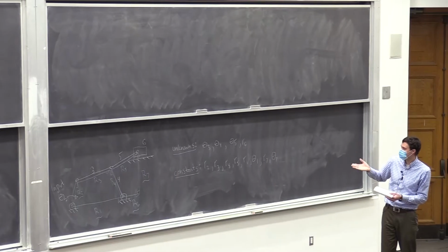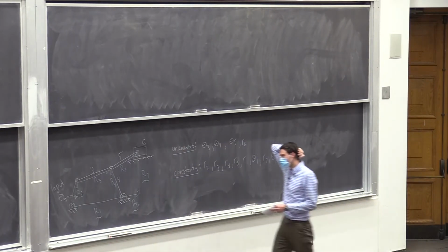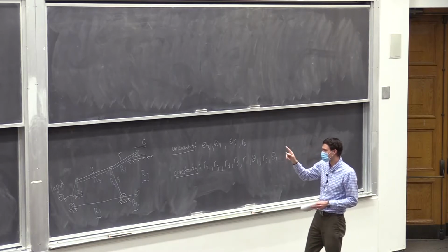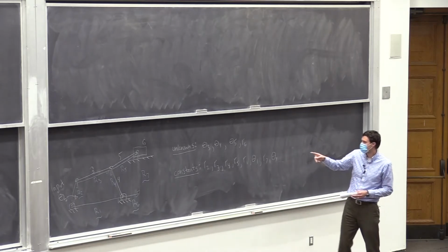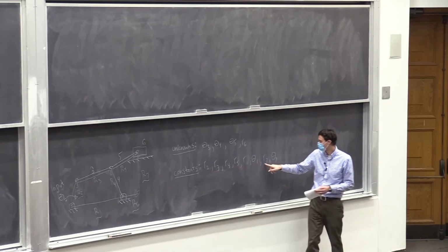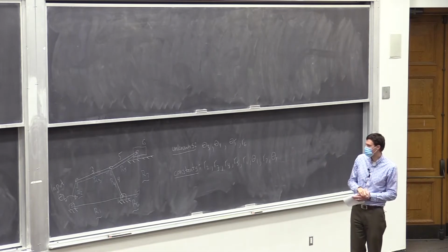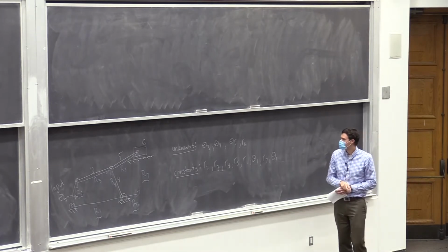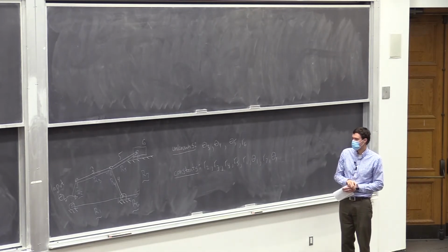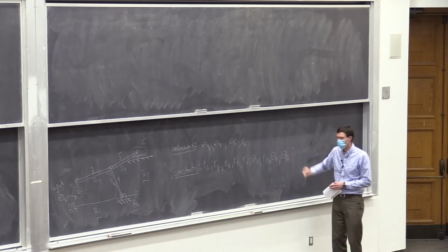So that's like our x position, our horizontal position of the output, length 6. Okay, so they should add up, including the input. We have how many? Is it 7? 1, 2, 3, 4, 5, 6, 7. 7 vectors, so there should be 14. 1, 2, 3, 4, 5, 6, 7, 8, 9, 10, 11, 12. Input makes 13. I'm missing 1. 6, yeah, theta 6. Theta 6 is always 0. So that goes here. So that makes 14.